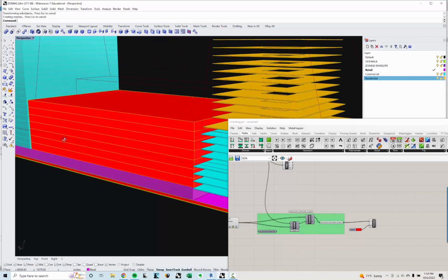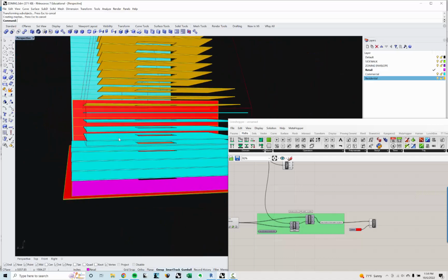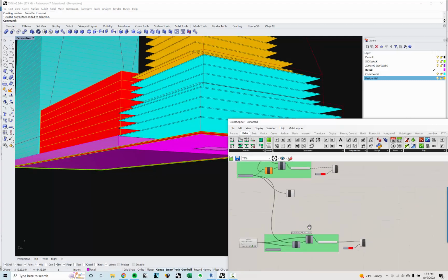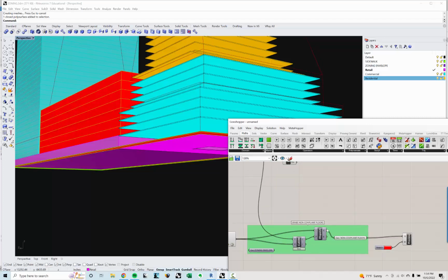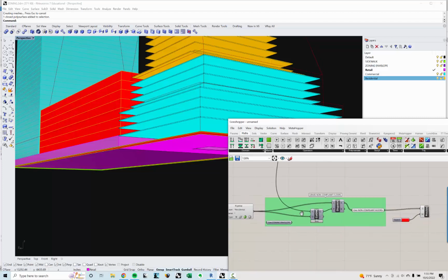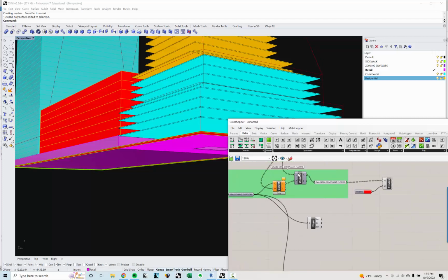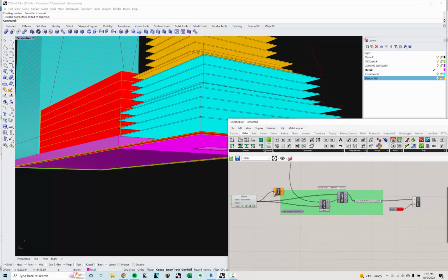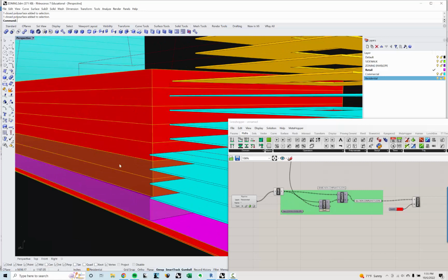Where is it breaking? These lower ones should not be. Let me just check to make sure that this is working properly. Residential, dispatch, non-compliant floors. True. Oh, I'm only getting one value back for true. So I think what I might need to do is graft. I'm going to graft this like the other one is grafting. Okay, that makes more sense.